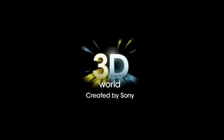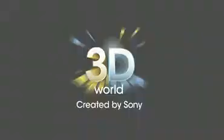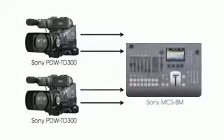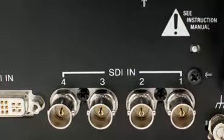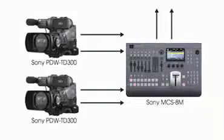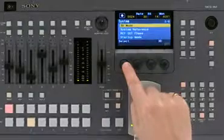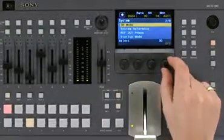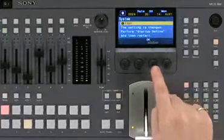When using 3D mode in the MCS-8M, the switcher will automatically tie inputs together. Inputs 1 and 2 become one left and one right, and so on. Consult the manual for connecting output settings. To set up 3D, go to Setup and select System. Switch 3D to On. The switcher will need to be restarted.